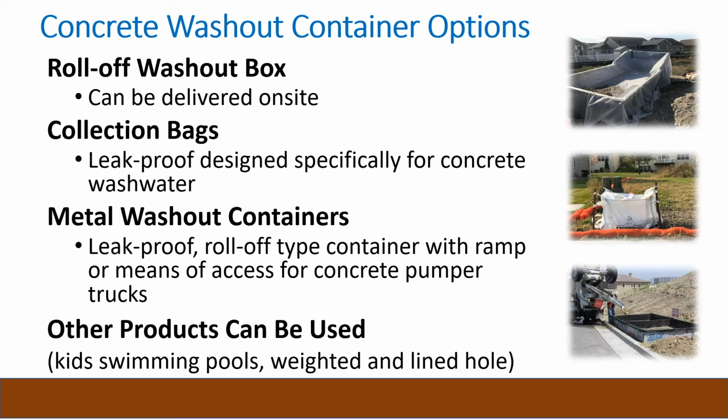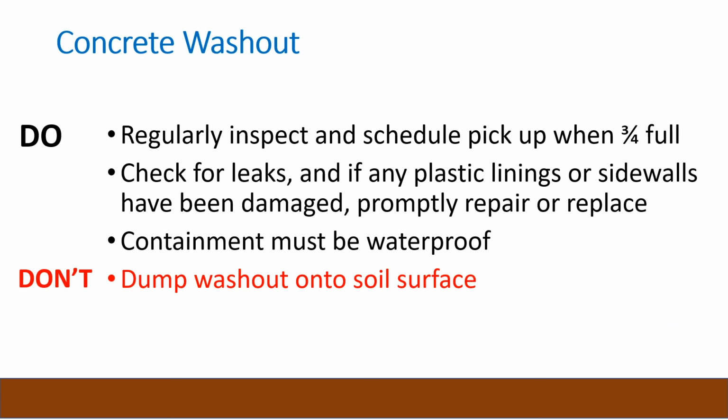There are washout container options that include roll-offs, bags, metal washout containers, and other products such as kiddie pools and weighted and lined depressions. Do regularly inspect and schedule pickup when 3/4 full. Check for leaks and if plastic linings or sidewalls are damaged, promptly repair or replace. Containment should be waterproof. Don't dump washout onto the soil surface.